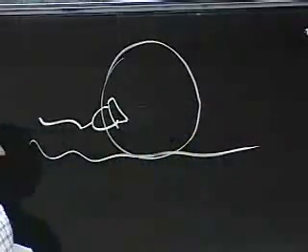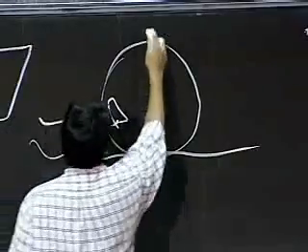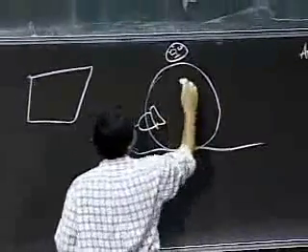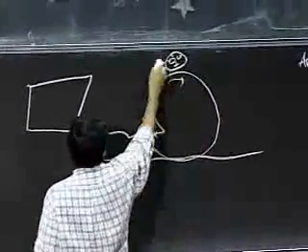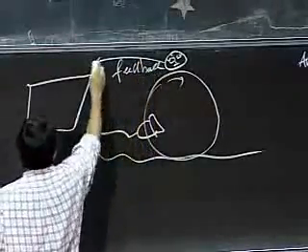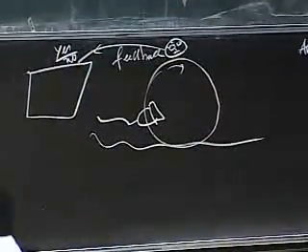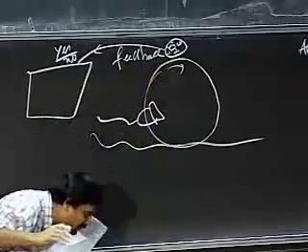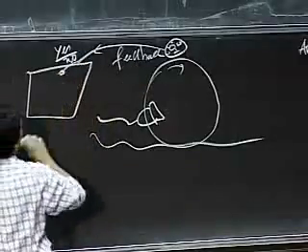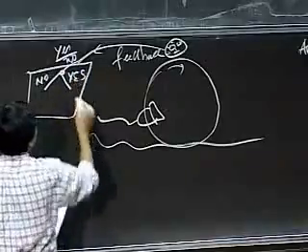The way anti-lock brakes work is as follows. There's a controller that sits here, and there is a little person looking at the wheel and seeing, is it turning? So this is a feedback. And it's saying, is it turning? Yes. Or is it not turning? No. All this person watching the tire is doing is saying, is it turning or is it not turning? That's it. That's a feedback path. It's a negative feedback.